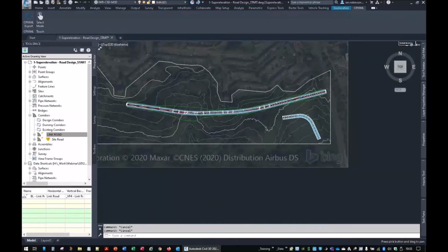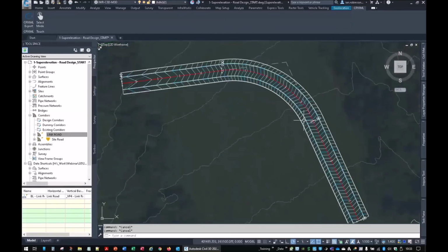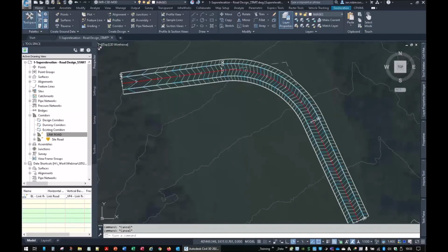Okay, let's have a look at a normal site road. So if you're doing like housing estates and stuff like that, you'll often go from a crown road up the hill, and then you turn around a 90-degree bend, and you're now on the, you could do the planar road in there. So here's a standard crown road. So let's do the same with this one. I'll just rebuild it now.